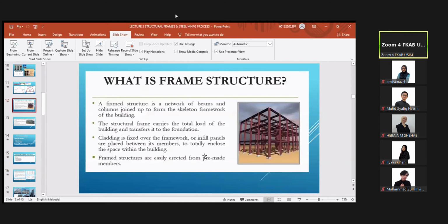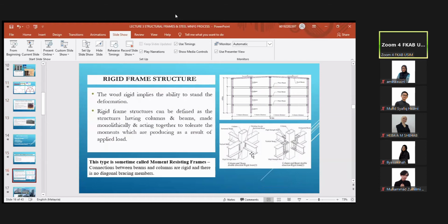This is a rigid structure frame. They are jointed by detailed jointing with rivets or bolts, so they become rigid. Of course, without bracing, the frame has to be big enough to support the weight and take all the lateral load, dead load and live load.